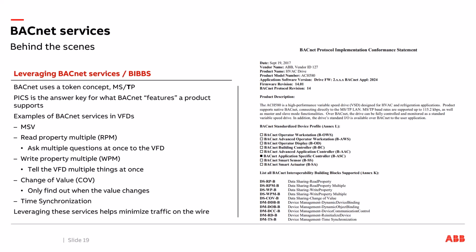Time synchronization, another really cool feature of BACnet. So I can calibrate all the real-time clocks. For example, drives have clocks in them. Typical drive, that clock might run 5 minutes fast or slow over the course of the year. So instead of having to reset it every couple of years, you can use the BACnet time sync feature, and BACnet, say at 4 o'clock in the morning every day, can go ahead and calibrate all the clocks on all the different pieces of equipment. It's great for troubleshooting, so that way your clocks are very accurate.